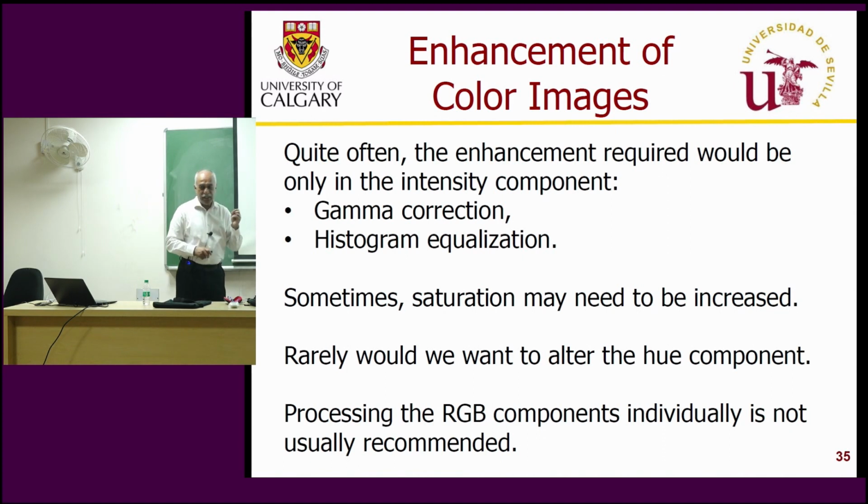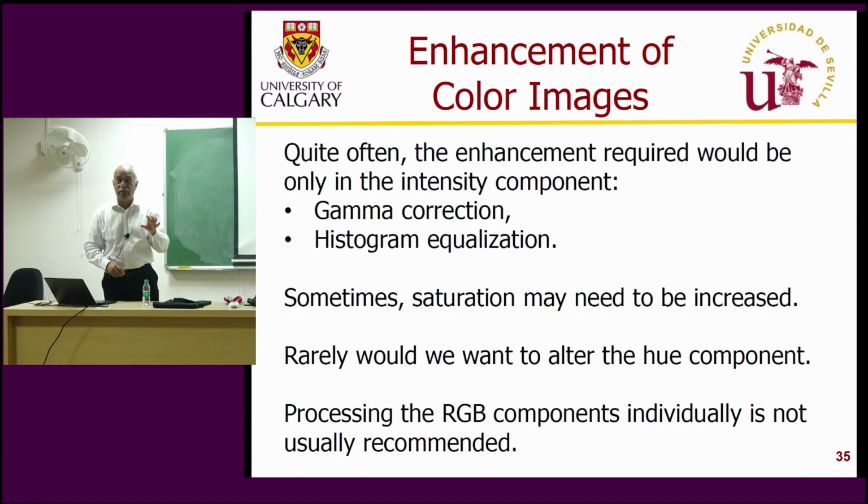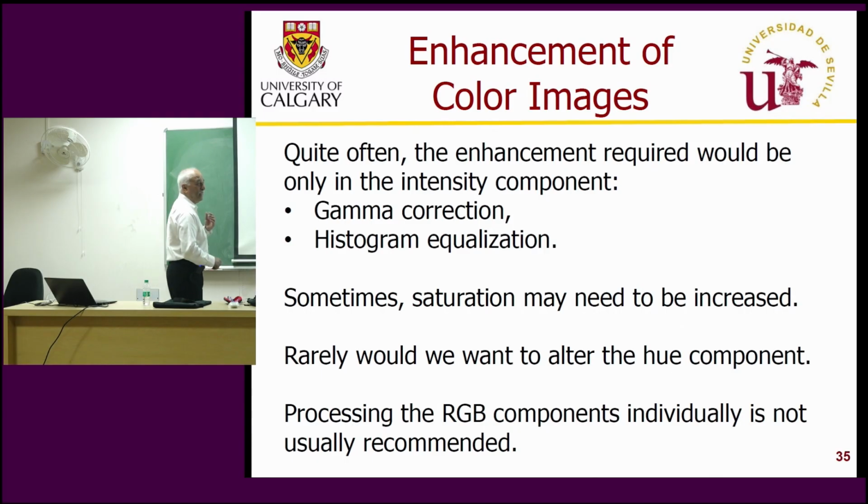Quite often the enhancement that is required, I'm not talking about noise removal, but contrast enhancement, is only for the intensity component. You don't want to touch color. You will assume that the color sensor has done its job. If not, do the color calibration using that color checker. For that, you must take a picture of that first and keep it for the same lighting condition. And do the color correction separately.